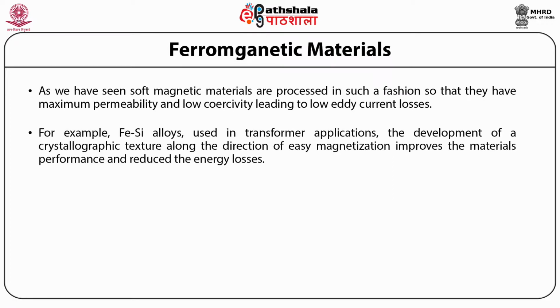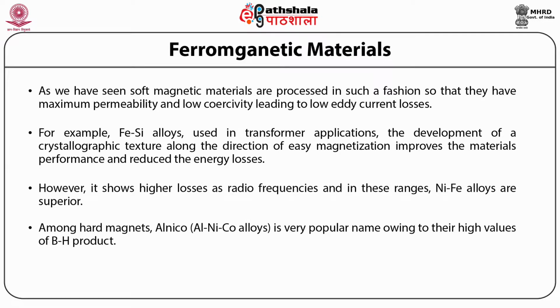For example, iron silicon alloys which are used in transformer applications, the development of a crystallographic texture along the direction of easy magnetization improves the material's performance and reduces the energy losses. However, it shows higher losses at radio frequencies, and in these ranges, nickel-iron alloys are superior.